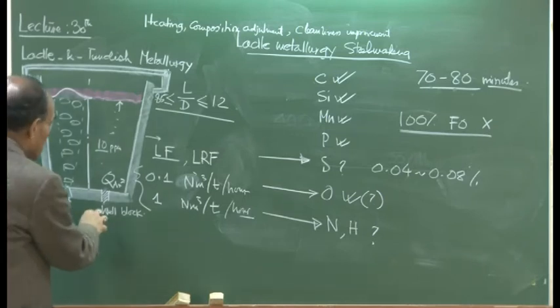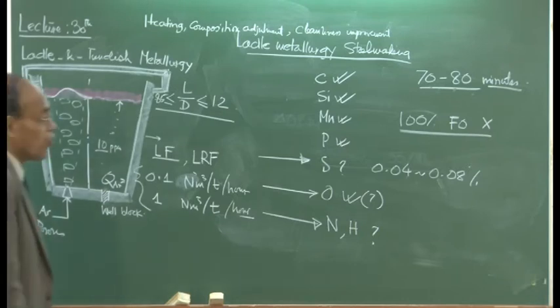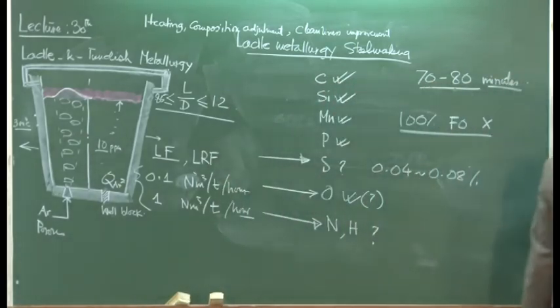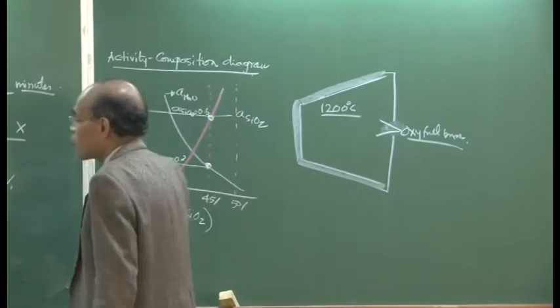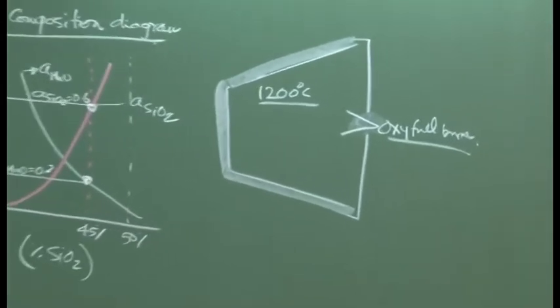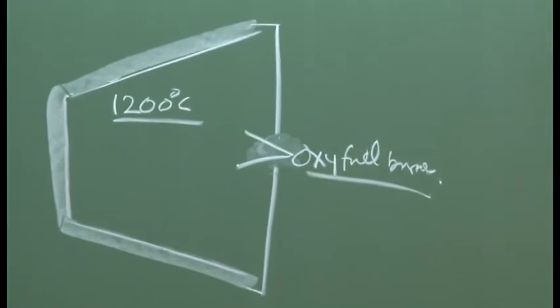So, the porous plug is going to be replaced every 7 to 10 hits, and we have the ladle recycling period somewhere between 70 and 100 hits, and so on and so forth. So, here I would say that once the ladle is preheated, with newly laid refractory, and the surface temperature is about 1200 degrees centigrade, only then is it taken to be used as an LRF or ladle furnace itself.